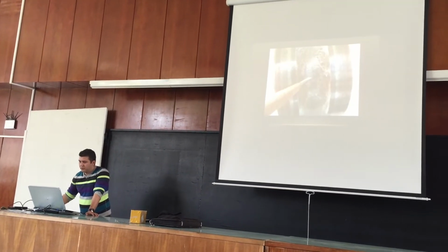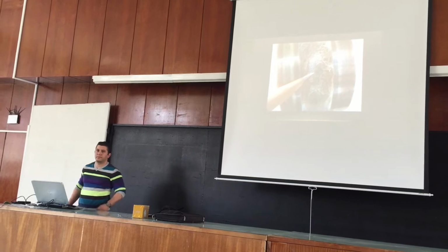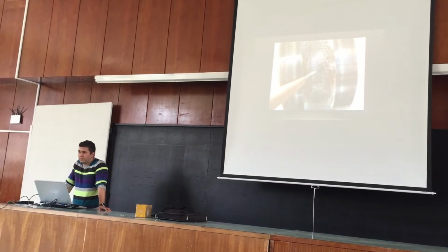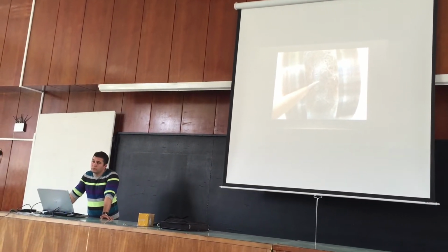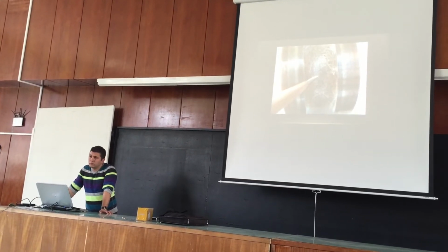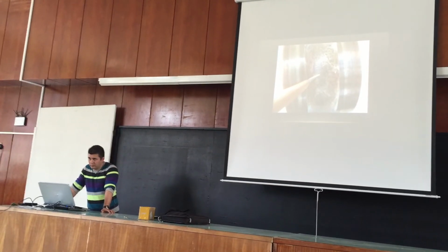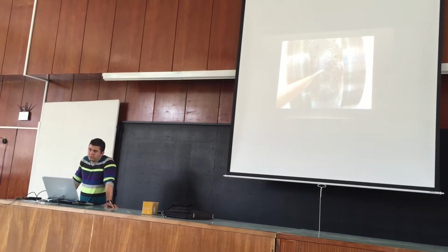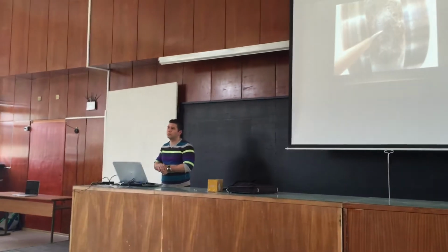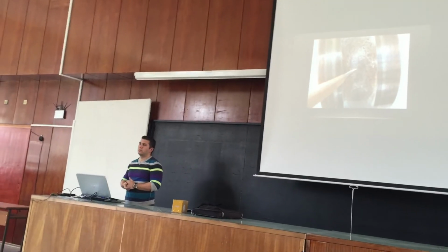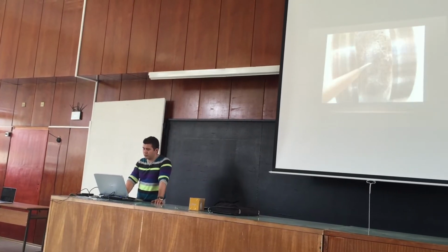Next picture. This we call a failure, and I'll explain it next time. We call this failure pitting, and it's a result of surface fatigue, but it's not because of lack of lubrication. This failure usually happens when lubricant is available between the contacting surfaces. There are many types of failure, but usually we have two specific types: with lubricant and without lubrication. With lubricant is this one, and the next picture as well. We call this pitting or surface fatigue. I'll explain next time.